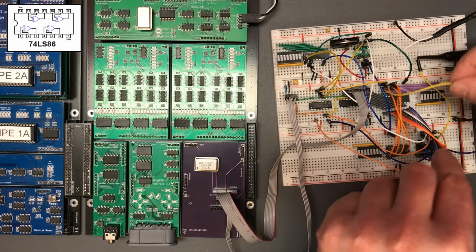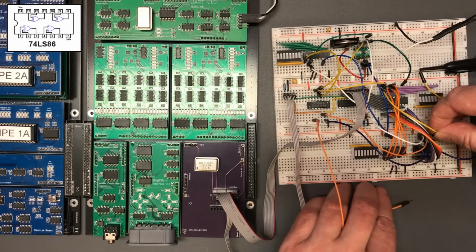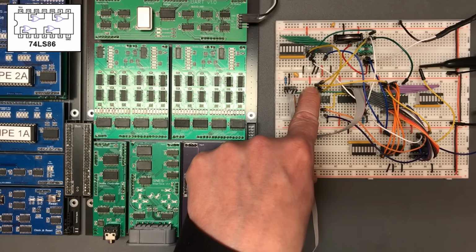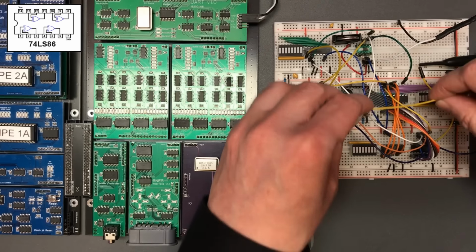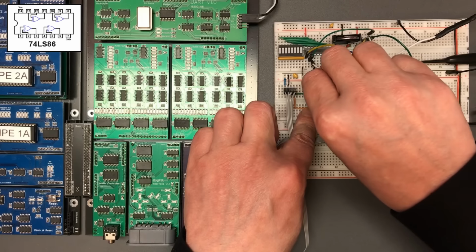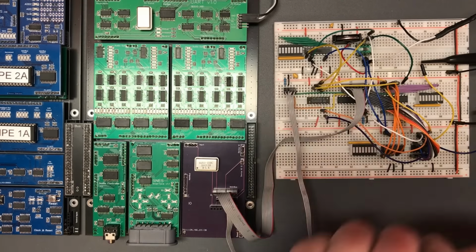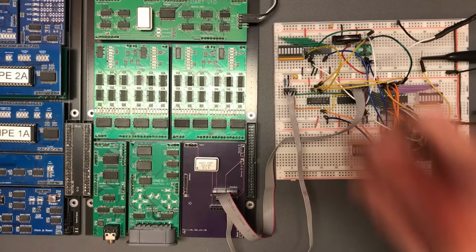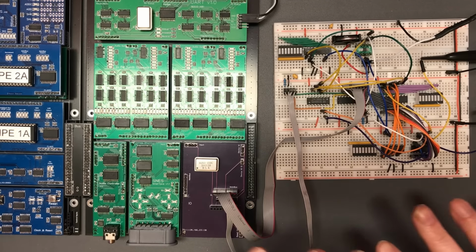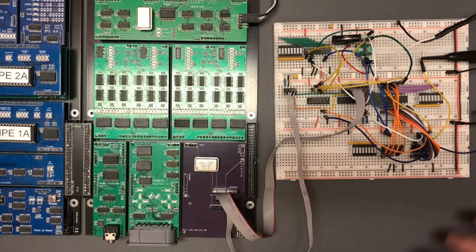I'll drive the clock line to our shift register directly, and then the extra input will be from this data line. Wish I had more colour varieties to make this simpler. It's clock related, so I'll make it yellow still. So in theory, this should work exactly the same if we've made the correct change to the circuit and the code change.